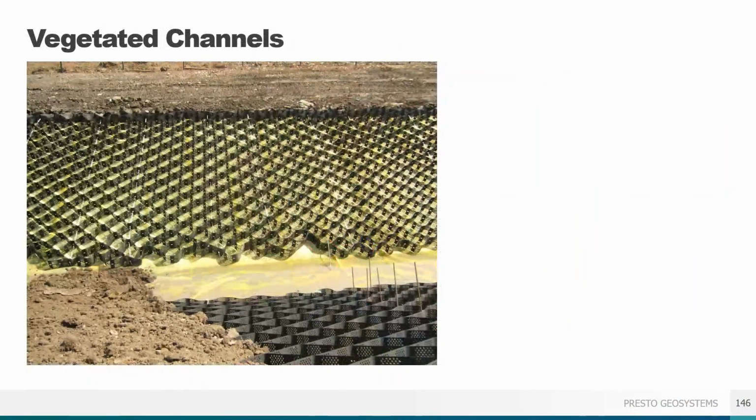Here's a technique tip for using the GEOWEB system along channel side slopes. Notice the panels just cover the sides, not the channel bottom. GEOWEB panels will allow for vegetation growth up both embankments, which will not normally be underwater. Notice the bright yellow liner below the panels. In this case, using the tendon anchorage system will hold the GEOWEB panels in place without damaging that liner.